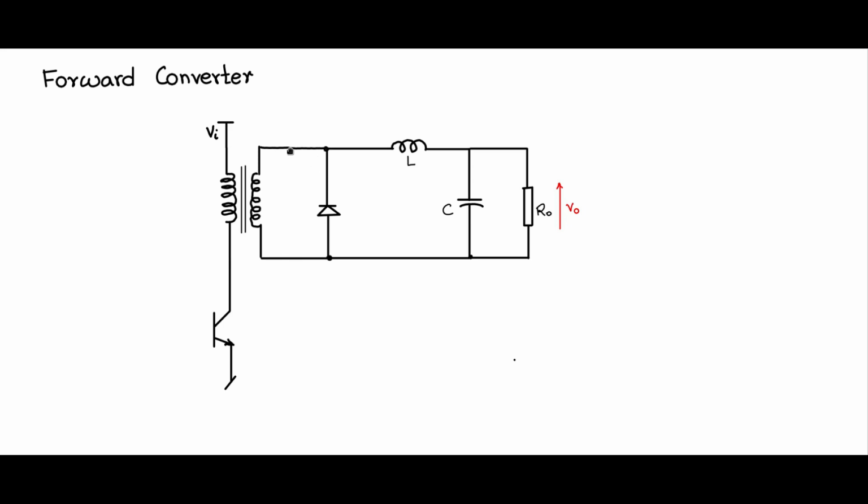I can't just join them up here, because let us say when the inductor is freewheeling, this diode is conducting and it is effectively shorting the secondary. When it shorts the secondary, the primary will draw a huge current and blow up this transistor. Therefore, we cannot allow shorting of the secondary when the inductor is freewheeling through this diode.